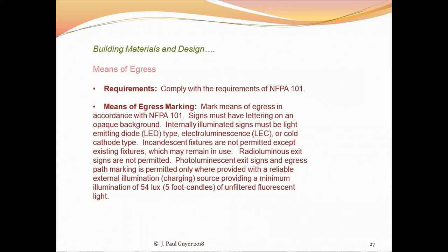But then you also have to consider the possibility that there may be blind or deaf people in the building, and so these exit signals, exit signs, now incorporate audible signals so that a blind person can hear the horn, or it might even be a recorded message that says something like move forward, turn left, move forward, turn left.